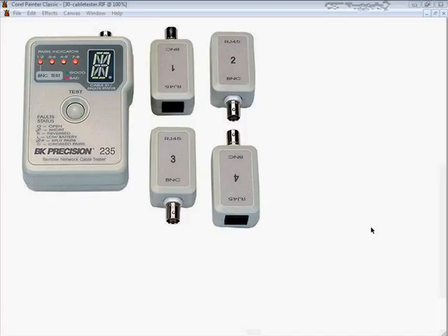These can do a continuity test where current is passed down the connection, and if there's a current, the connection's assumed to be a good one. There's also a resistance test where a known current's passed down the connection and the voltage that shows up is measured.